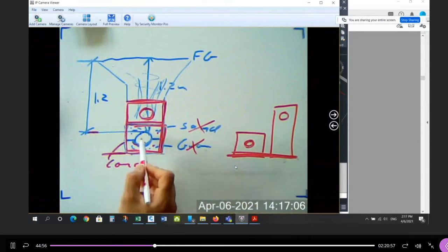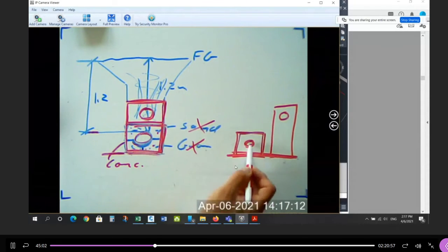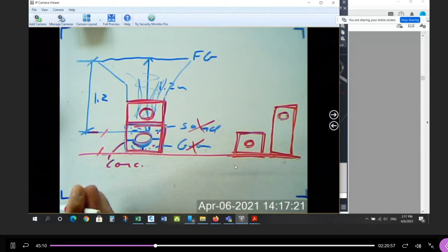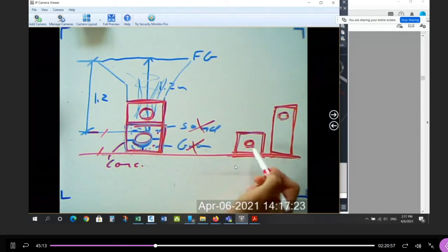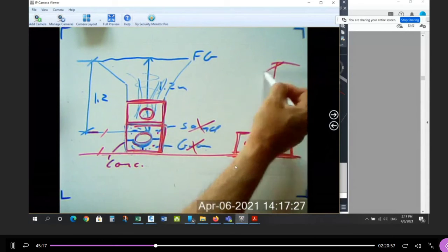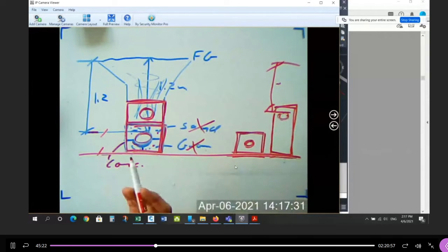Here's the original hole down at the regular level. We concrete encase the whole thing, so the bottom is here. If we raise the pipe, we don't raise the bottom of the concrete. So now what you have is a block where the bottom is well below the frost. And that's the trick in being able to not have cover. This is less than 1.2, but really frost can't act.